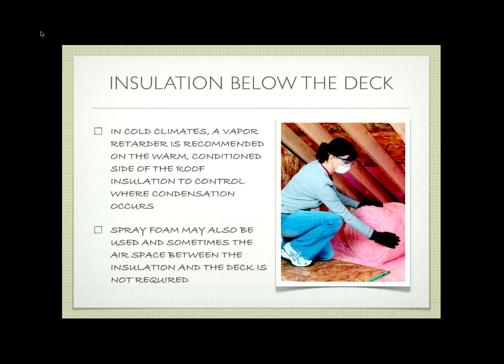So the big question comes with, we're now in California. Where do you put the vapor barrier? You could argue that it could go on either way, depending on what season it is. So this is why, typically in California, we don't put them in. So we use in California, and this is becoming more common, what's called Tyvek. And that's the brand name for this.